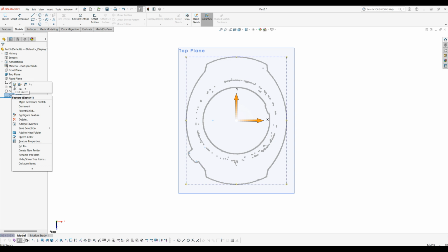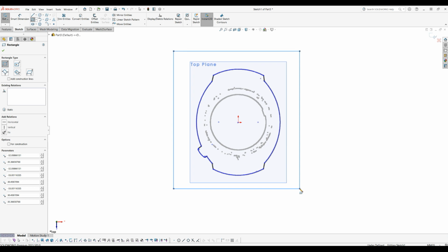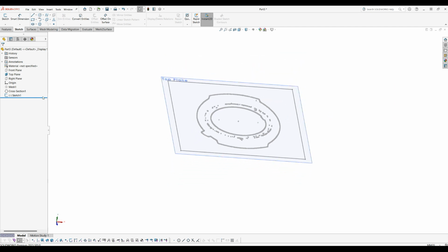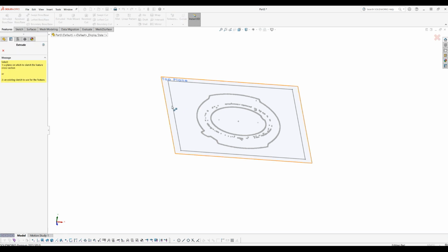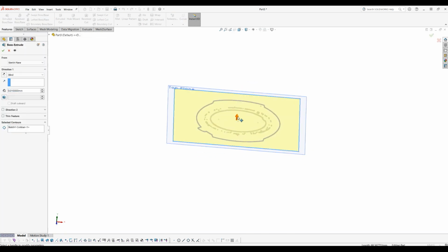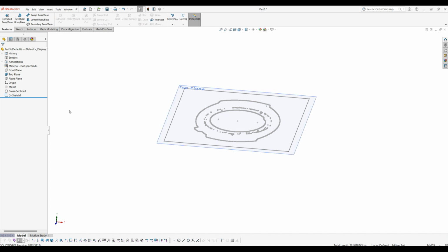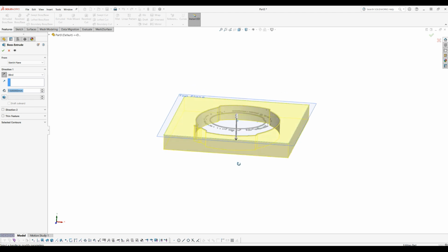I'm going back actually to edit my sketch. What I'm going to do is just to create my bigger shape. Feel free to create the dimensions here and make it centered and so on. Now I have my sketch, and I'm going to use the extrude command of SolidWorks that will take this and will just drag and create this for me. Actually, this is not something that I did properly, so probably I need to create a sketch and then extrude. This will make it in the right way. Now I need just to drag to create my shape.